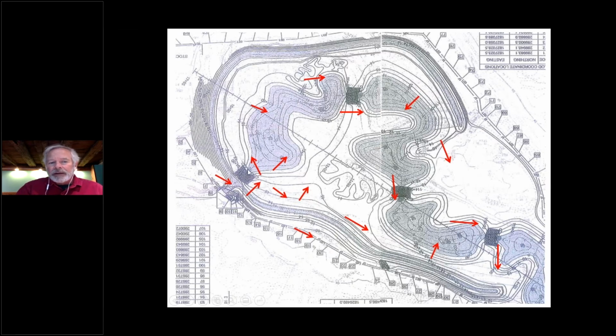And then the only way for that water to get out, as we've said, is either for it to flow over, and it's a level spreader in that case, so it doesn't cause erosion, and then you have a lot of water in contact with a lot of plant material, or it drains hyporheically because it's at a higher elevation than the ground, so it pushes it through to get through that sand, that carbon-rich sand, into the pools.